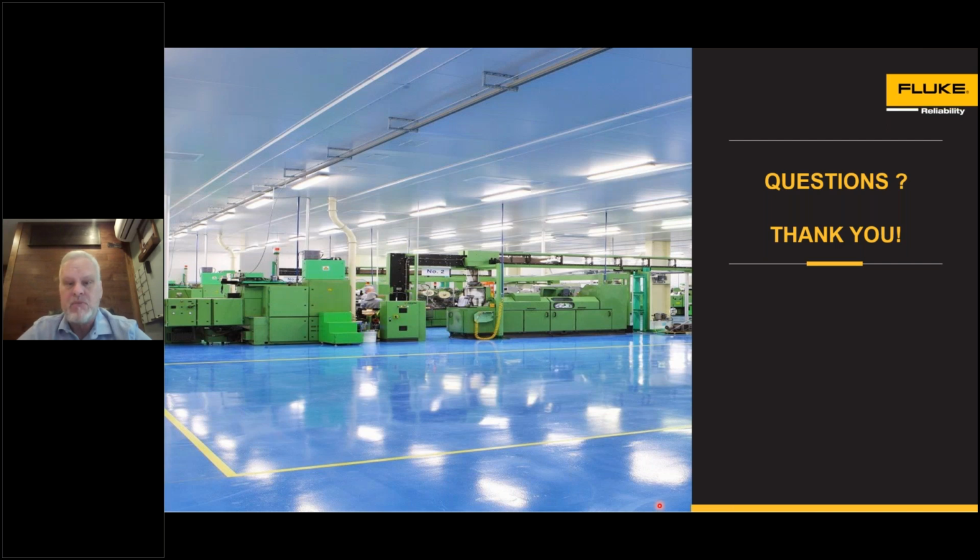If you're wired and your wiring runs 10 meters away, and you're picking that up with some device. This may tie into that previous cooling tower question, where cooling towers are inaccessible, and oftentimes you will be 10 meters away from that motor. The wireless device in this case would still have to be mounted directly on that machine. In the case of a cooling tower, obviously during the setup that would have to be locked out, put in a safe condition, the sensors would have to be mounted, and then that data would be transmitted hourly and daily out to a gateway, which would then go to the cloud. Whereas wired accelerometers, in those same scenarios, are attached to the machine, again, during a lockout, tagout period. Cables are run out to the outside of the machine to some sort of junction box, and then a portable device is plugged in, or an online device is permanently connected. Those are the scenarios in which I understand the question.